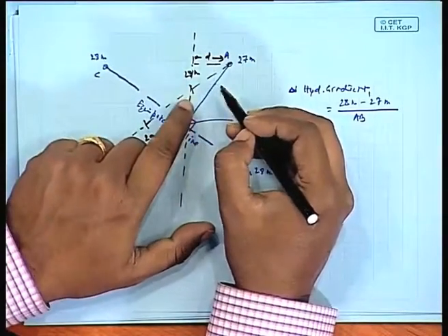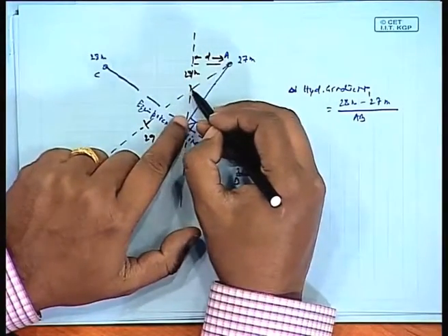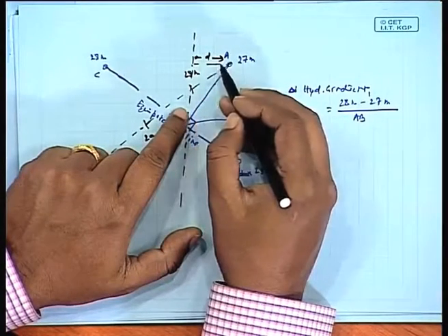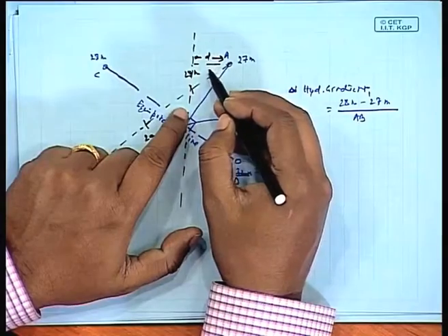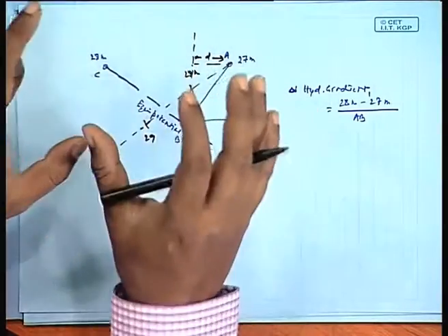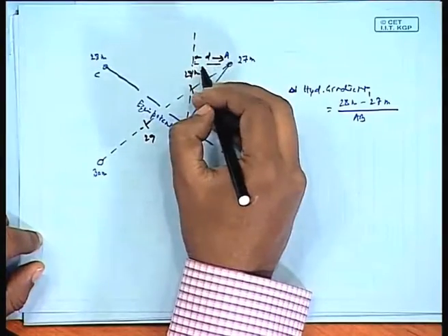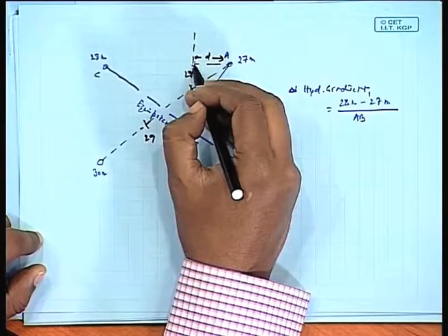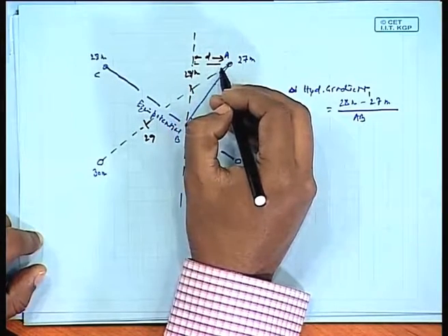In such cases, we are going to find another equipotential line, considering the 3 points. We find the perpendicular distance from that point to the equipotential line, and divide the head difference by that distance.